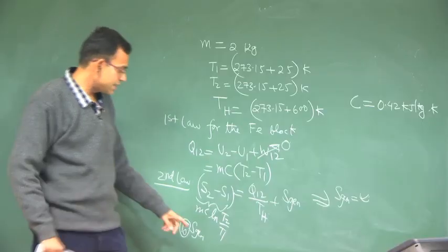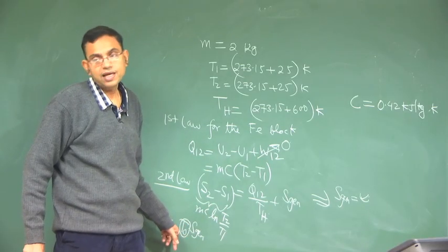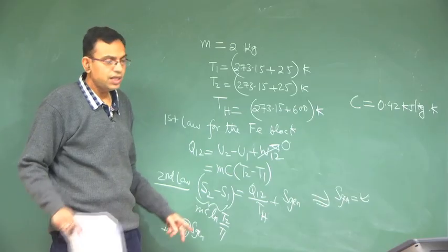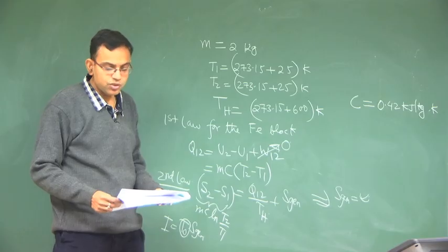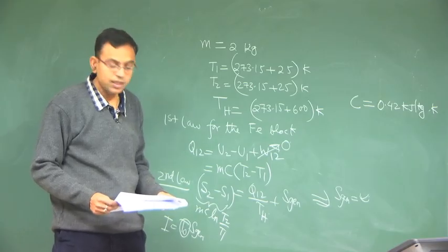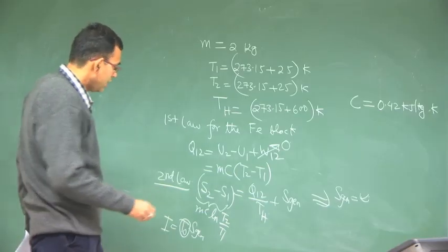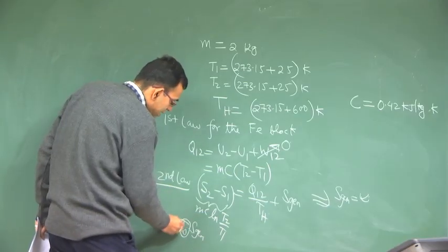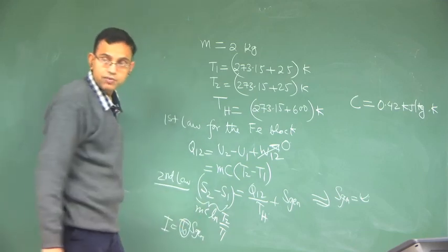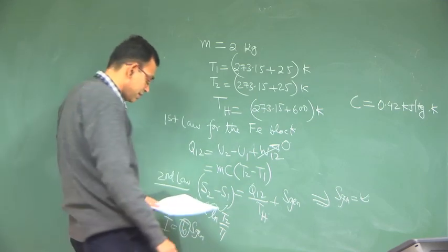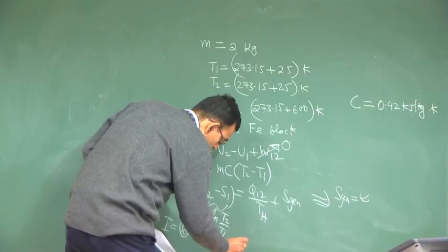Normally this is called the exergy reference temperature, which is the ambient temperature. So, in this problem the intuition is that the ambient temperature is 25 degree centigrade and not the 600 degree centigrade, right. So, then if you put that as T0, this will give you the irreversibility, and the irreversibility in this case is 96.4 kilojoule.